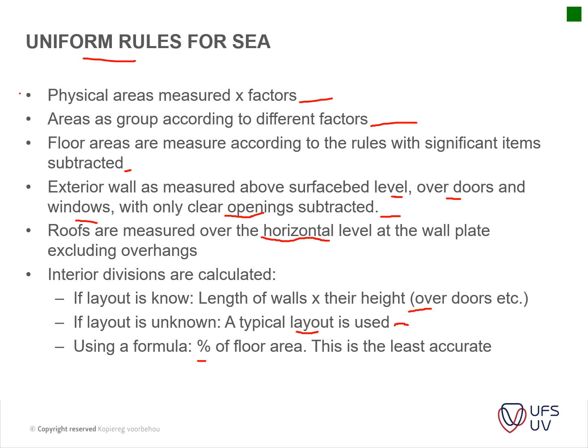So you can use a percentage of your interior walls. You can again use previous buildings if the interior layout is not given yet, and just factor in what percentage of the interior layout is walls. Okay, so these are the three methods that you can use to actually calculate your interior divisions.